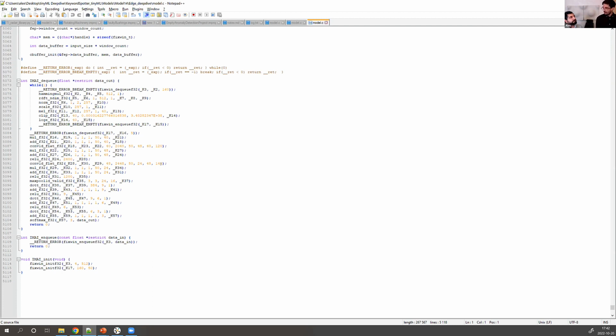And you have an example of that, a customer of ours. Exactly. We had a customer with a very constrained chip, so they didn't want to run any kind of operating system or scheduler. So they calculated how long it takes to go through this DQ function, which goes through all of the layers in the network that we saw earlier. Then they split it up into sections.